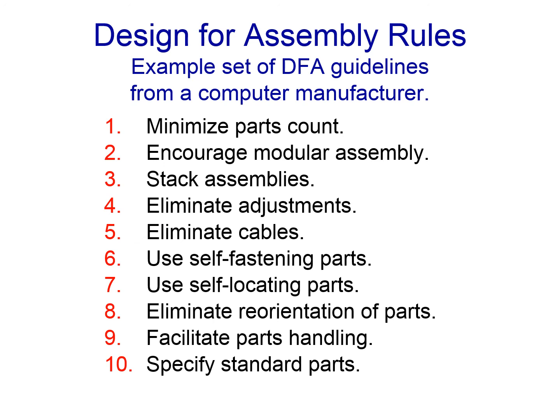Stack assemblies, sometimes called Z-stack assemblies, mean that if we can assemble things in the Z direction, basically XY being the horizontal plane and the Z being the vertical axis, then gravity will actually help us. It helps us to stabilize the parts, so you don't need to have tooling and fixturing to hold the things together while you go to other things.